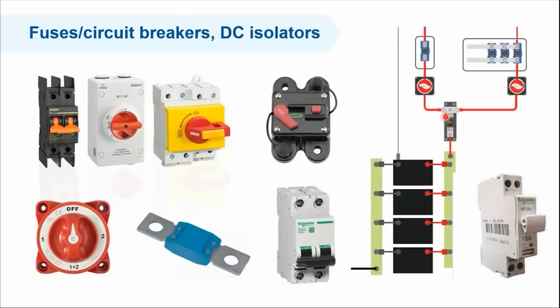Once the fuse has blown, no more current will flow into the circuit, so this is an open circuit, and this really protects. A general rule here is that fuses not only protect the devices and the batteries, but they protect the wires first.